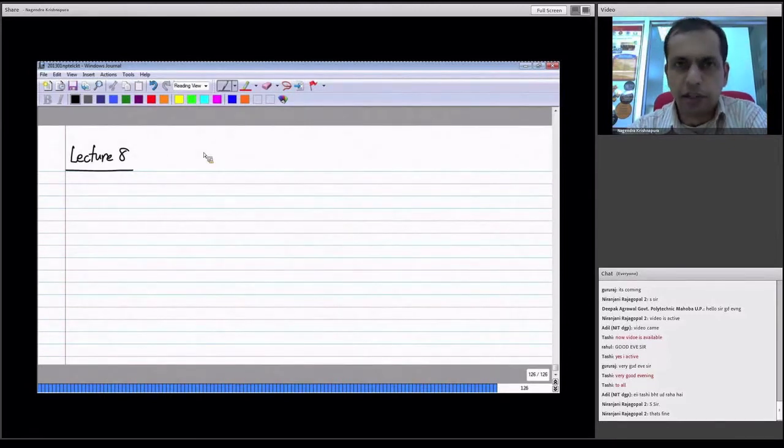Now, when you have control sources, when you have a voltage controlled current source, then all it does is add some terms to the conductance matrix, so that it becomes asymmetrical. Okay, and other cases can also be handled in the same way. When you have a voltage controlled voltage source, you will have to again either define a super node. If you are doing hand analysis, that's the preferred method because it reduces the number of equations. Or if you are setting up the equations for analysis by computer, then you define the current through the voltage source as an auxiliary variable and also write down the equation for the control source.